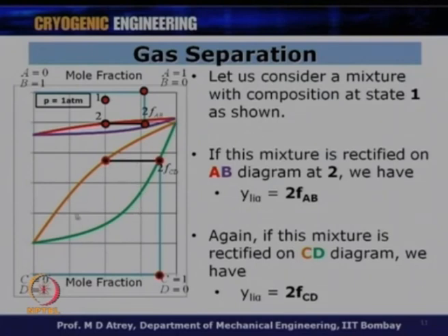If you have a boiling point difference from this to this, right in the first condensation, you have come very close to 90% mole fraction of C. The first condensation itself has separated component C, and the liquid has around 90% of component C, while in this case it was around 75 to 80% only.